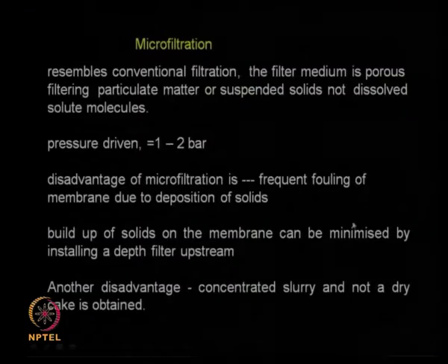Because there are pores, the pressure required is also much less. You use 1 to 2 bar. It is almost like the normal filtration where we also use 2 or 3 or 5 bar pressure. We do not go very high in pressure. But the disadvantages of microfiltration are just like your normal filtration. There is going to be deposition of solids, frequent fouling of membrane.